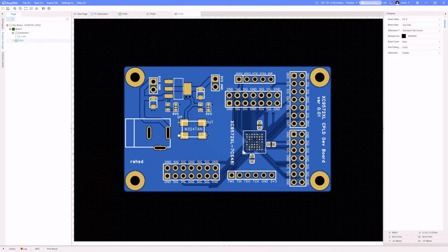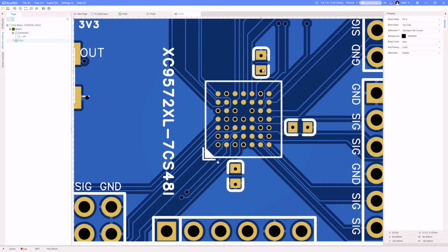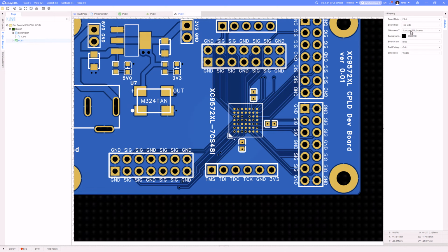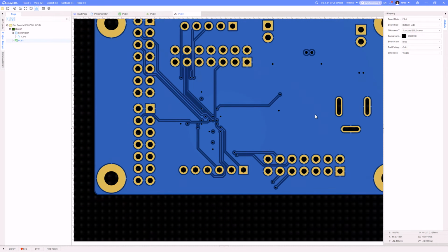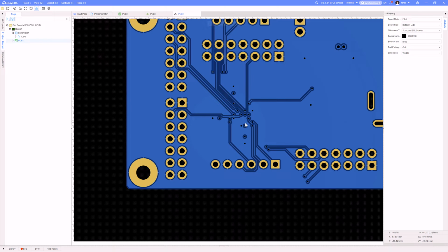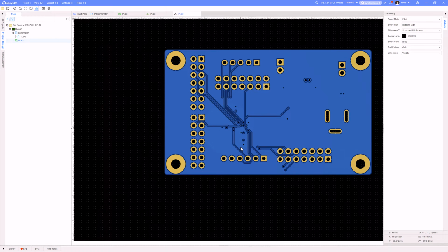This all looks fine. If I look at it in this view, you can see where I did via and pad. So I just did via and pad for these capacitors. You can see which of the BGA balls I did a via and pad. In other words, I'm dropping to the bottom side. So some are dropping down, going out the bottom. Some are going out the top. I can change this to the bottom side if I want to see what that looks like. And there I can see those specific ones that I dropped through on the vias.